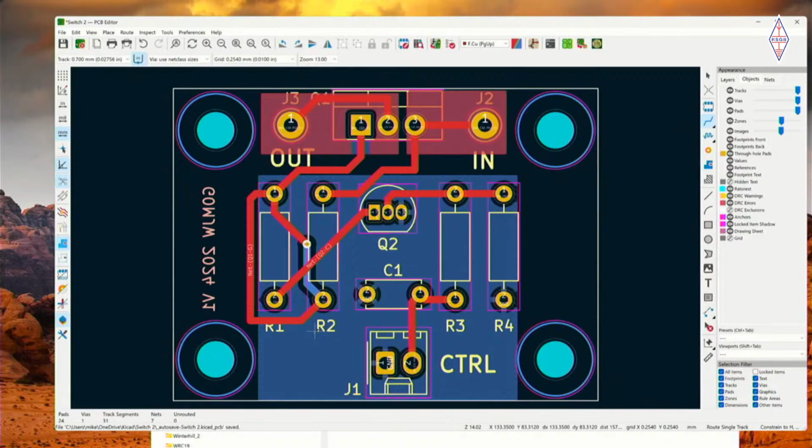Now, when you're designing a PCB that's complicated, you very quickly get tied up in knots. The way to resolve that is to set yourself a rule where you do horizontal tracks on one side of the board and vertical tracks on the other. That will allow you to route most boards on 2 layers relatively easily. If you start waving around like I've done here, because I knew it was a simple circuit, it rapidly gets very difficult to route, and you end up unable to do it. So that's the way to do that: horizontal on one side and vertical on the other. Yeah, good point.